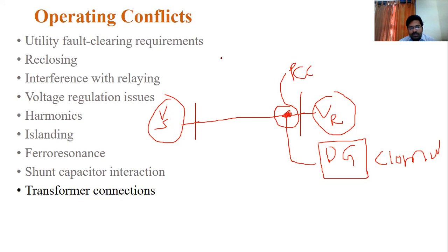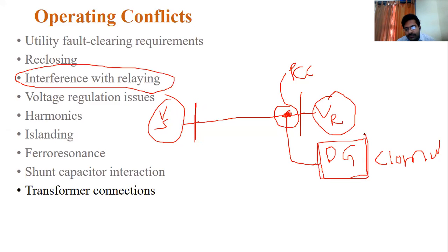What are the requirements for adding this DG to the distribution system, and what reclosing equipment do we give to the feeder as well as the DG to protect from external as well as internal faults? And how are the relaying equipments used here? For the feeder, we separately maintain the relays, and at the same time, DGs also maintain their own type of relays.